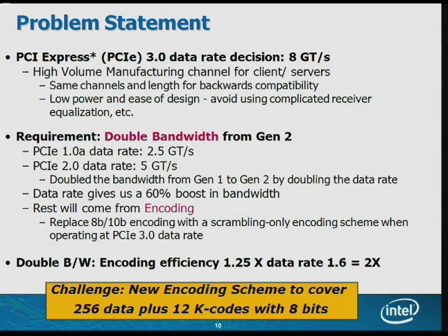And one thing, if you're familiar with 8B/10B, is that it was a very simple way, by creating so-called 10-bit characters, to create the control characters in a serial data stream that allow framing of the packets and also support some special low-level protocol signaling messages. If we remove 8B/10B, all of that is pretty much gone. So we actually needed to step back and figure out how to recreate, through the new encoding scheme, a notion of these special characters.